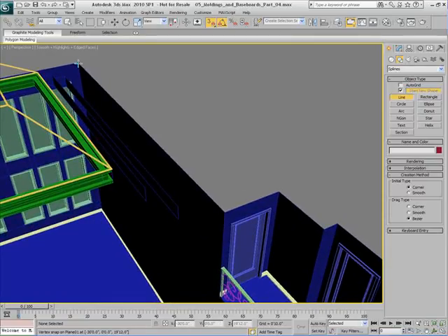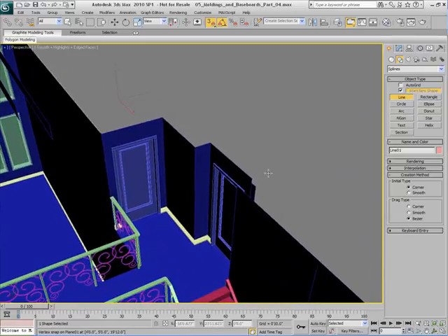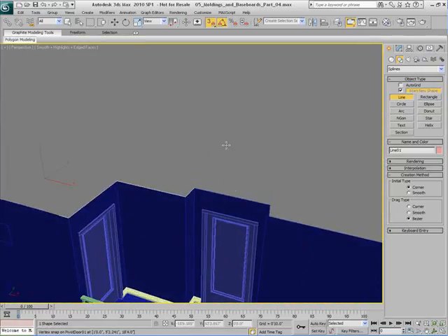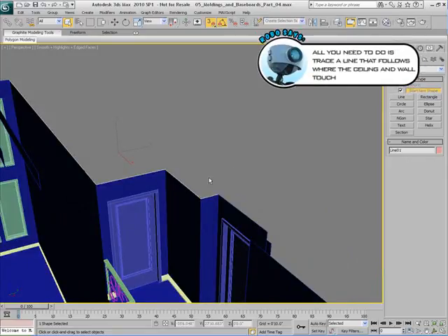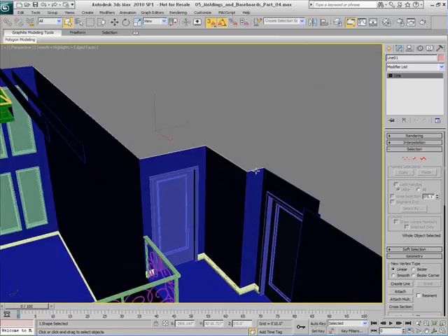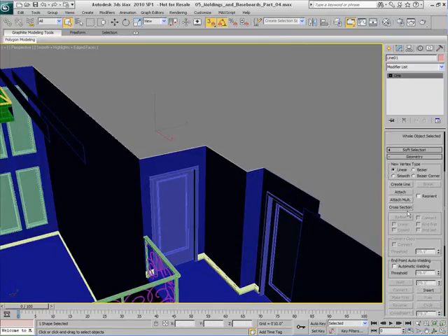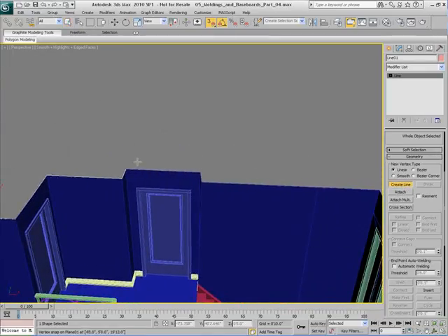I'm going to snap a line over here and start creating a line. Basically, you can see how we can create a line. Just start clicking on the different vertices of basically the corner of the ceiling here. Now when you run out of room, just go ahead and pan over here and right click to end the creation process. The line should still be selected. Go to the modify tab, okay, and down here we have a little tool here. It says create line. If we go ahead and click that, we can continue creating our line. So let's go ahead and do that.